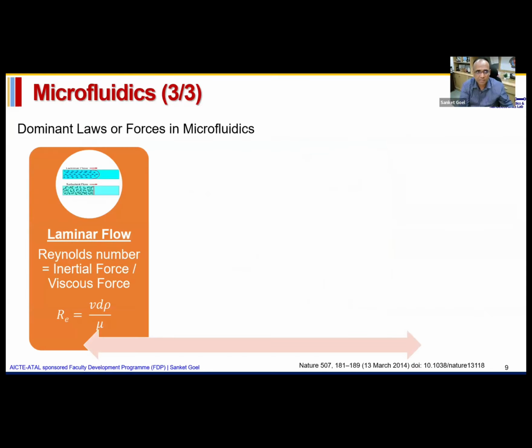So this is the major difference in the two. The three major laws I want to share with you, which are governing the microfluidics, are mentioned here. For the first one, the liquid is laminar. We're not talking about the turbulent flow, which predominantly happens in an oil pipeline or water pipeline. The flow is very smooth.